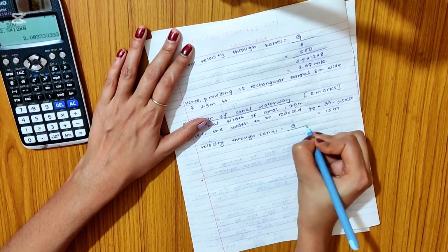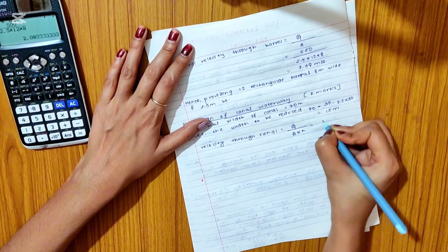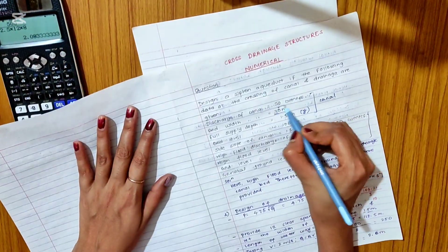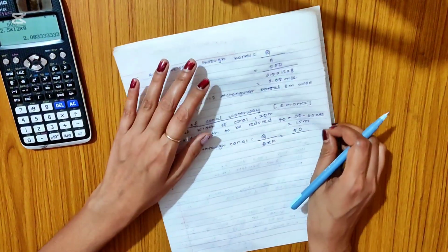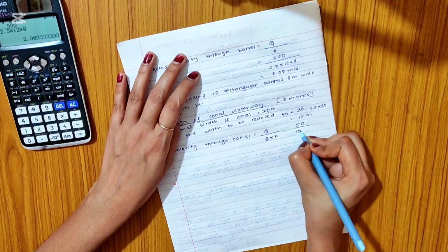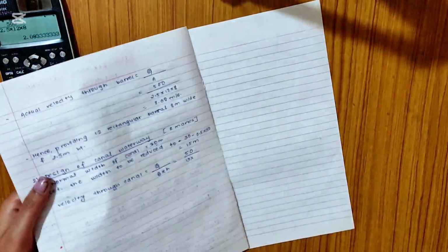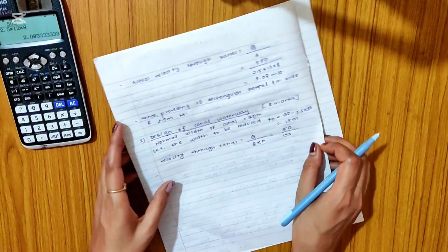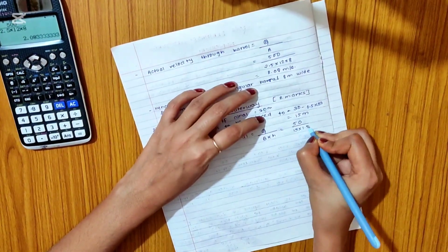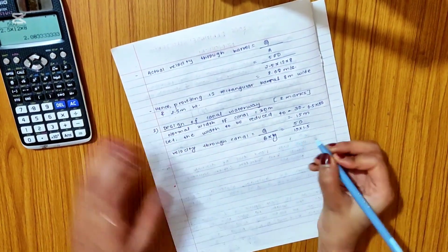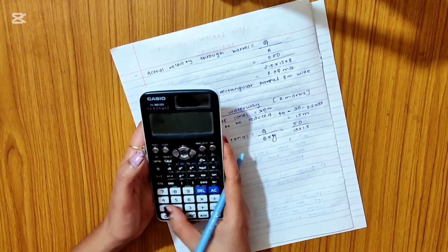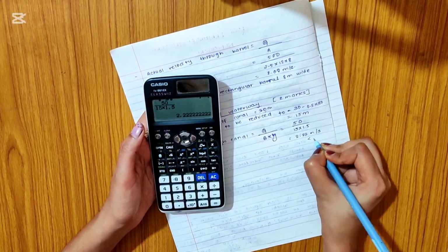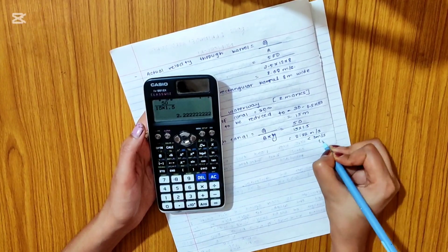will be equal to discharge by area, that will be the breadth into the height. The discharge of canal is given as 50 cumecs. So 50 by B, that is 15, into height H, the full supply depth, which is 1.5 meter. So 50 divided by 15 into 1.5 is equal to 2.22 meter per second. This is less than 3 meter per second, so this will be okay.